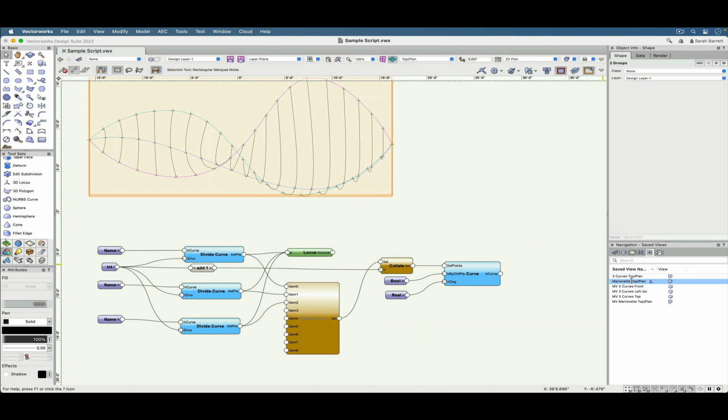Interpolated NURBS curves pass directly through the points used to describe them, but control point NURBS curves do not necessarily pass through the points. And for a degree of 1, NURBS turn sharply at each point, while a degree of 3 is the typical default curvature of NURBS. With the degree changed to 3, the curves have the smooth shapes that we want.